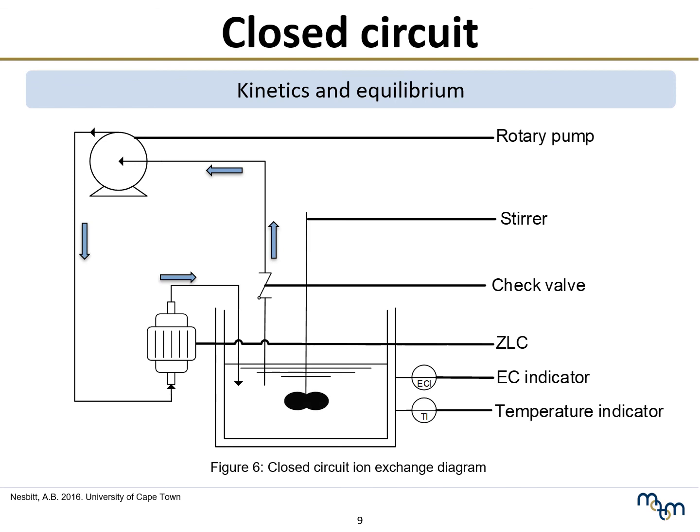The kinetic testing is required in order to determine how quickly gold recovery is reached under specific conditions. This involves varying flow rates with a fixed liquid quantity contacted with the resin. This type of testing determines how much time is required for gold to be recovered for each specific resin, therefore formulating absorption isotherms for the synthetic and actual leach solutions.